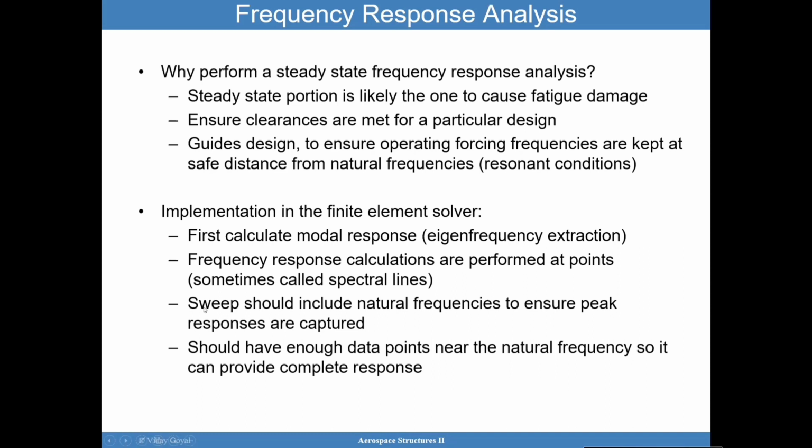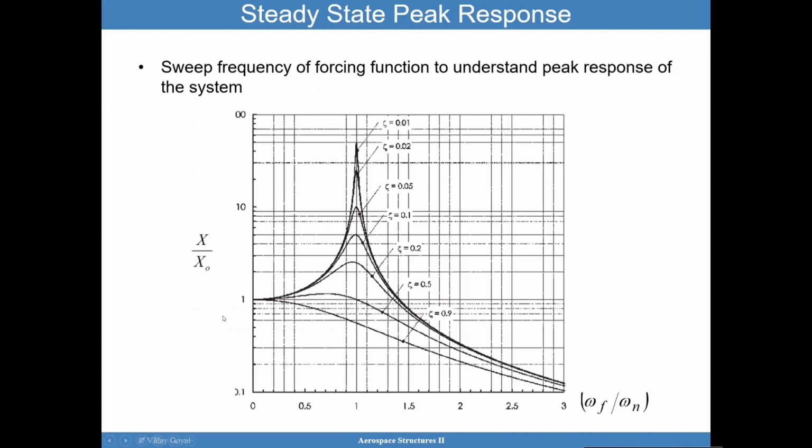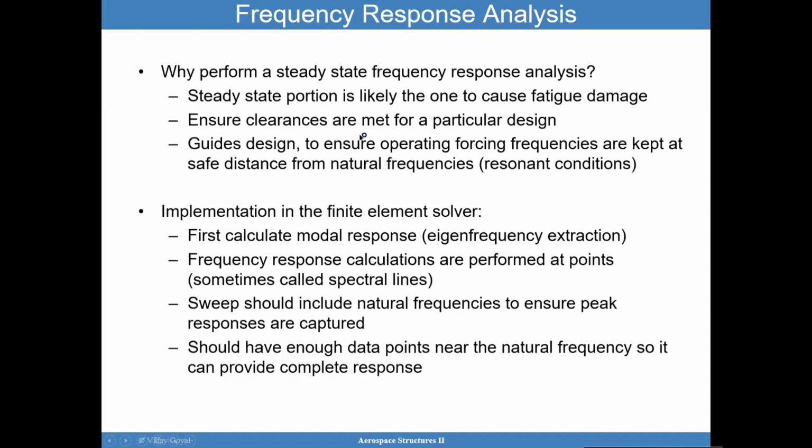We also are going to then take this information to understand where to evaluate the response. Like, what is the point? If I know the natural frequency is here, it doesn't make a lot of sense to be looking out here. It makes more sense to be looking near the natural frequencies. And that's why getting that first step is so useful.